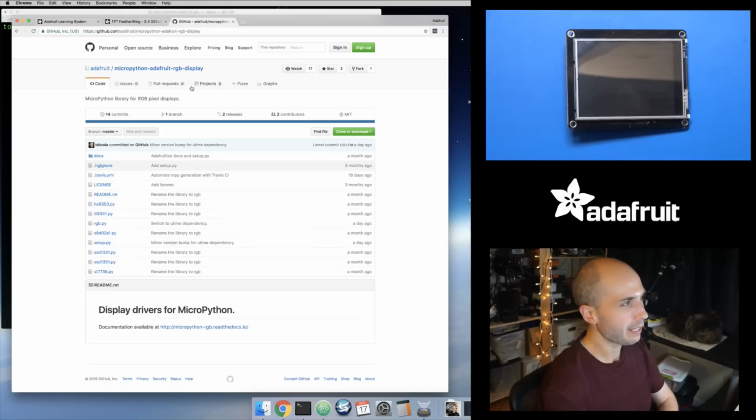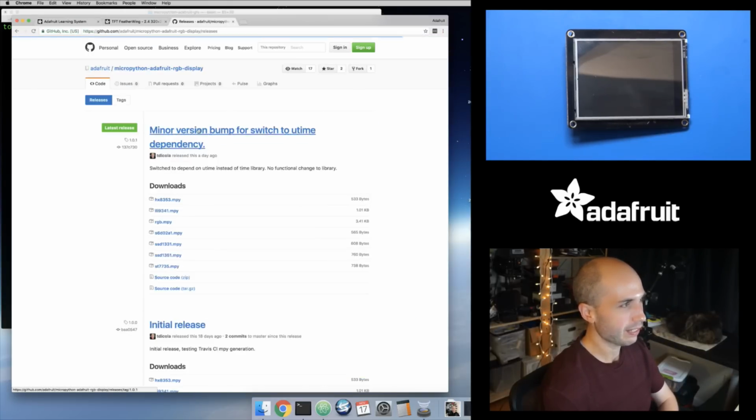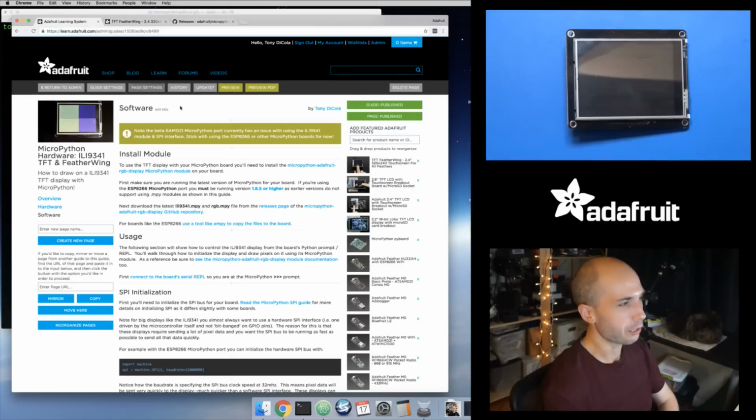Anyways, you can find these under the releases tab of this library, and there's a link in the guide that shows this. So here all the .mpy files are. You want to grab rgb.mpy and ILI9341.mpy, and I've downloaded those already. Then you want to copy them onto your board. For the ESP8266, I'm going to use the ampy tool. I have a link in the tutorial if you haven't used that before, showing how to use it. It's just a tool that copies files onto MicroPython boards.